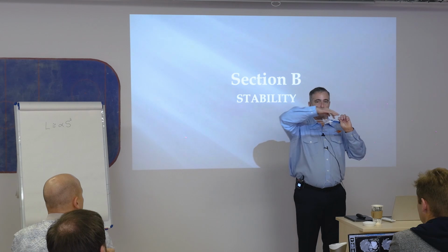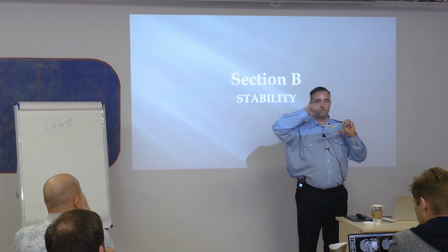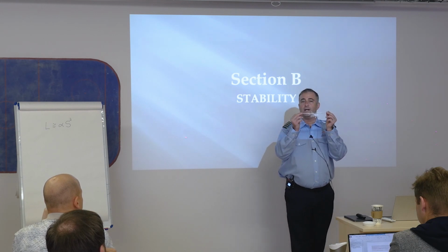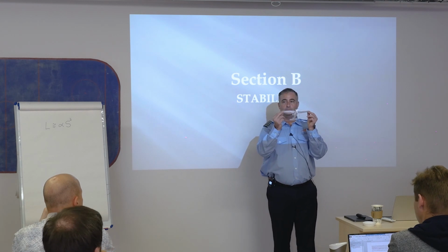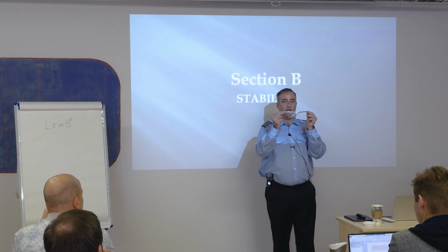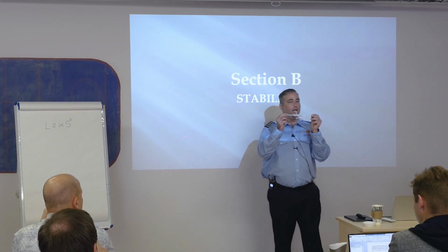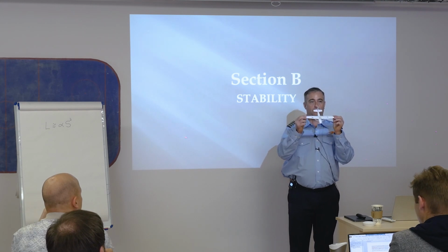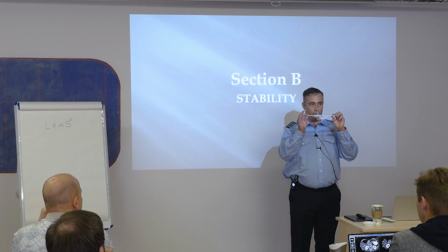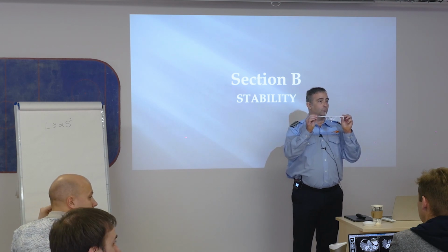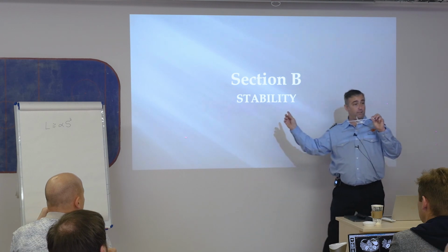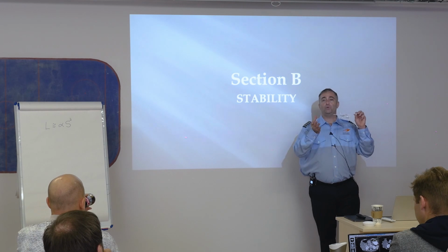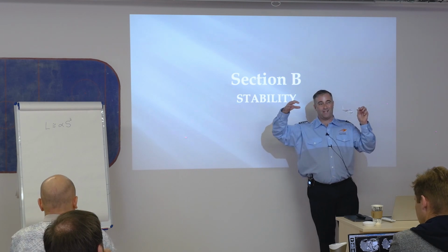Lateral is this, all the way across left to right, okay? They cross from the center of gravity. So the lateral axis describes my pitching motion of the airplane, pitching up, pitching down. And I have a control surface for that. The elevator. That makes me go up and down. The stabilizer is going to help me for stability. On the back side of that stabilizer is an elevator. And those two things could be formed together for a stabilator.